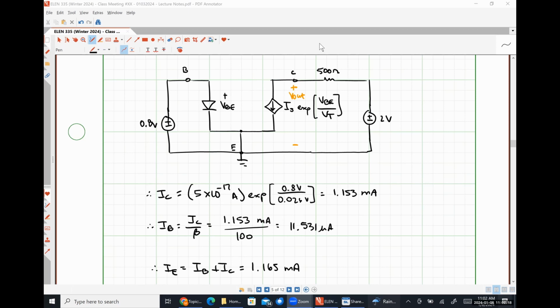So instead of doing a bunch of difficult math, I can just use this normal linear math, just simple algebra, and then add those two results together. So realistically, we are doing kind of a superposition type thing to where we're adding the effects of the large signal and the small signal together and calling that the total response of the system.